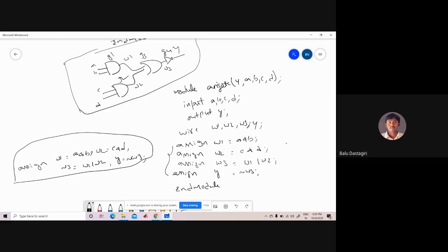This is one of the ways you can assign them, or else you can assign them by using multiple continuous assignment statements. So you can use the single assignment statement, or you can use multiple continuous statements here. The semicolon terminates the continuous assignment statement. Whereas the comma separates the different assignment statements in the given continuous assignment statement. This we have to remember.